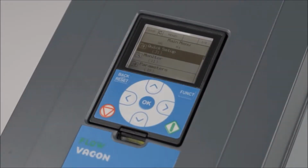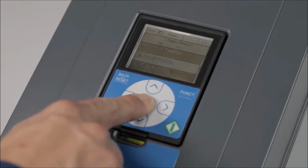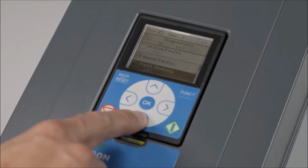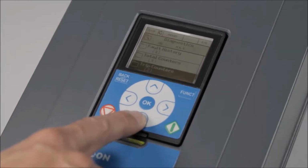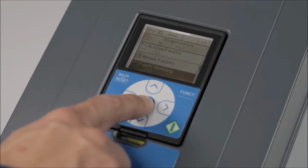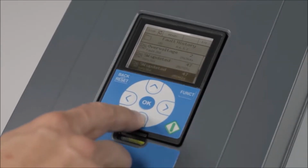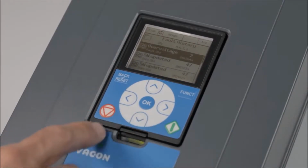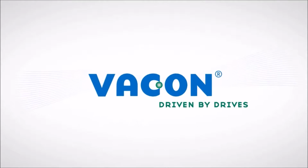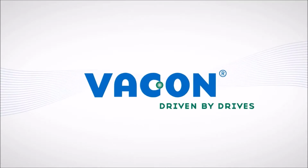In the Diagnostics section, users can find out information about active faults that may occur. If the drive has tripped out on a fault, access the list to check the latest faults history. You can reset faults here, get information about which software versions are used, and check drive counters such as running time or kilowatt hours of energy taken from the grid. Further information can be found in the VACON 100 product pages or in your product's application manual.